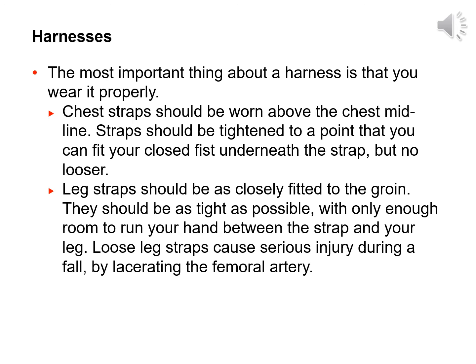Leg straps should be closely fitted to the groin. They should be as tight as possible, with only enough room to run your hand between the strap and your leg. Loose leg straps cause serious injury during a fall, by lacerating the femoral artery. Harnesses that are worn too loose can cause a person to fall out of them during a fall event, thus rendering the equipment useless.